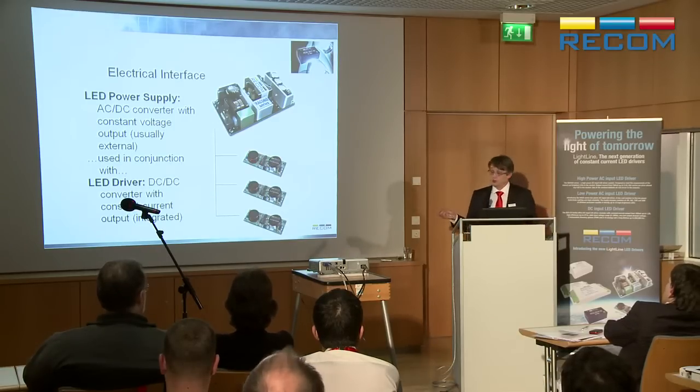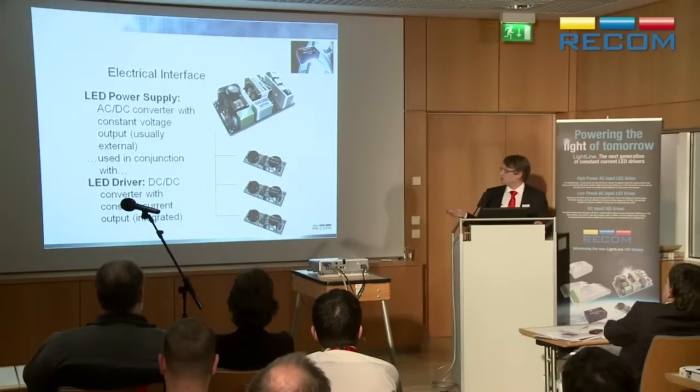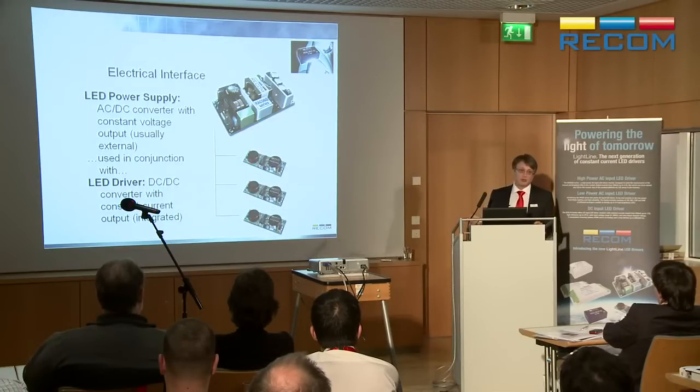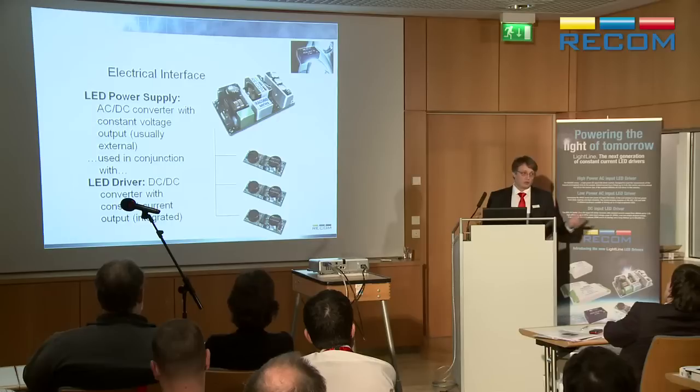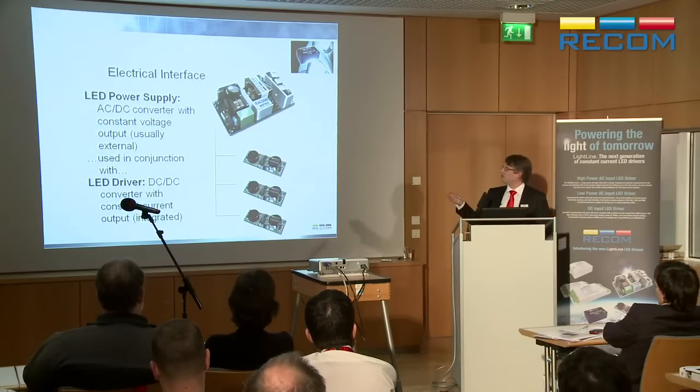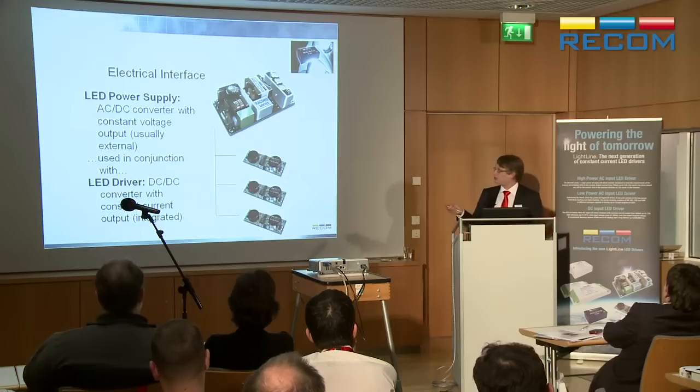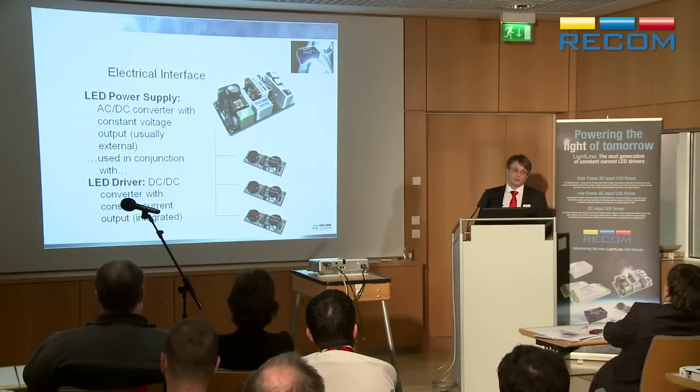And you can either integrate them. Integrate them means you mount them on the same circuit board where your LEDs are. So we also have options, for example, SMD mounting drivers, because most LEDs are SMD. So if you're doing a long strip light, you put your SMD process to do all of your LEDs. Then you want a driver that's also an SMD. You do it all in one process then. So we offer everything. We offer this part, we offer the through hole, we offer it with wires, and we offer it with SMD.